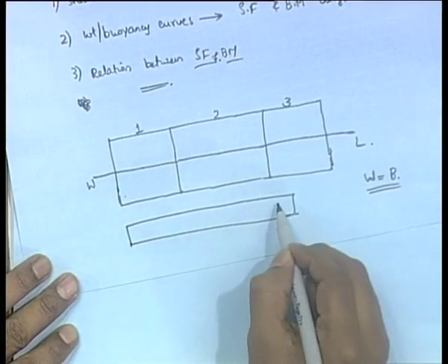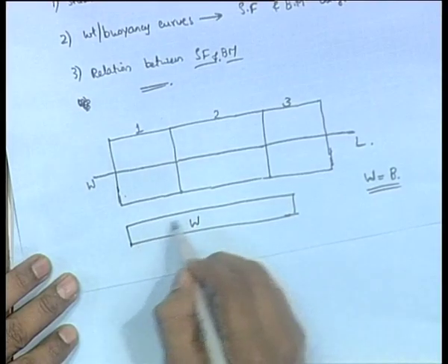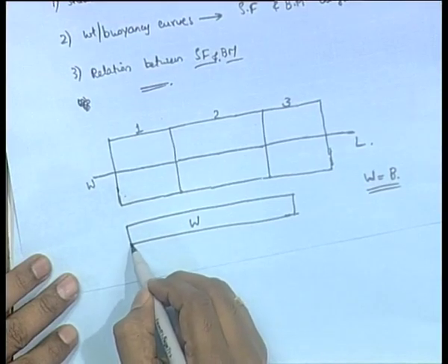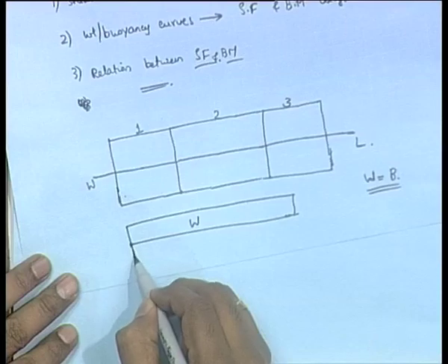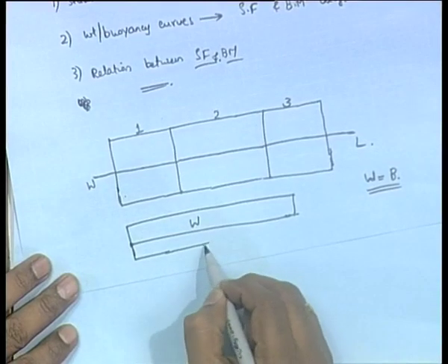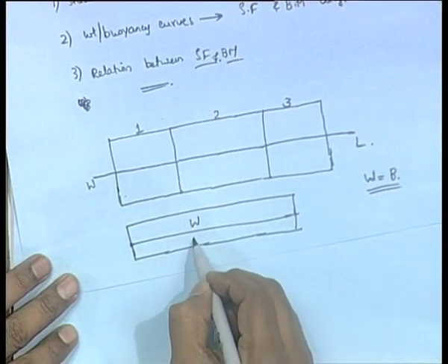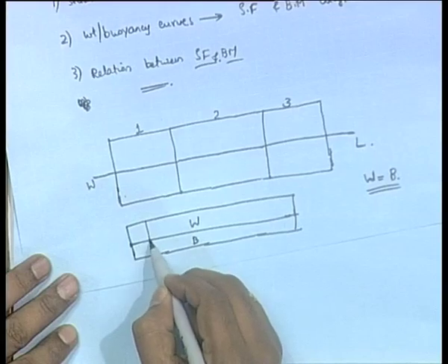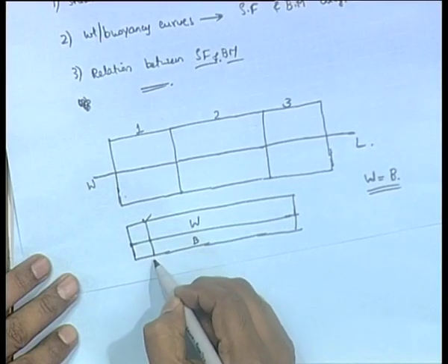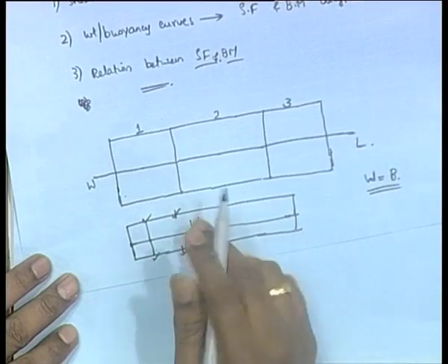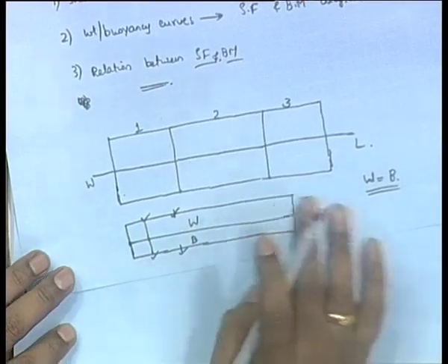weight is uniform, it is constant, this is what I meant by a straight line, this weight curve is like this, and the buoyancy curve is in the opposite direction. So let us put it as negative. So buoyancy curve is also like this. So these two are exactly cancelling out each other at every length of the ship, everywhere it is cancelling out. Here this and this cancels out, it cancels out entirely along the length of the ship, and there is no problem here.